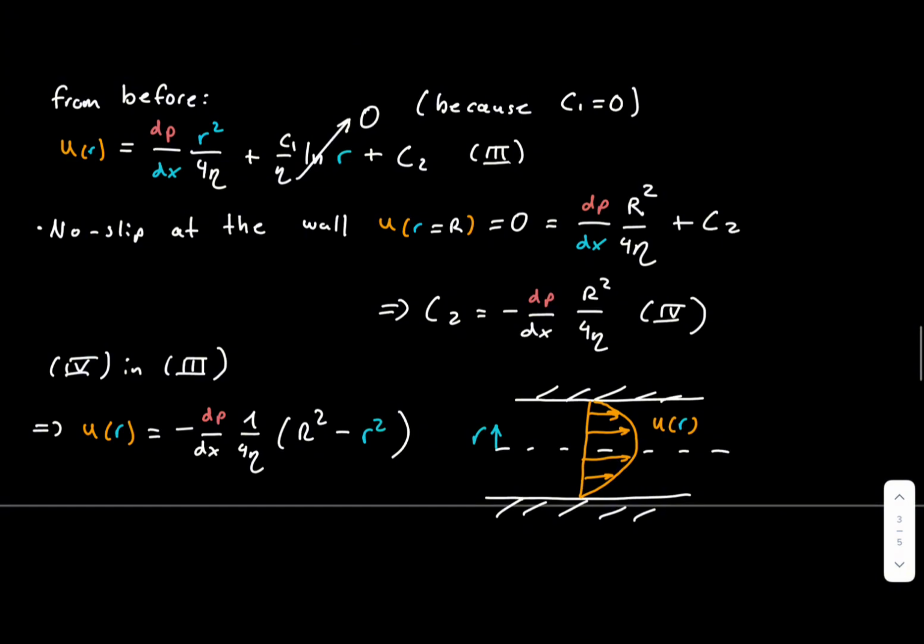And that's the full strategy. Define the geometry, choose the correct control volume, write the momentum balance before choosing a fluid model, integrate once for shear stress, choose the constitutive law, integrate again for velocity, apply symmetry and no slip boundary conditions, and finally check the signs and physical meaning. If you master this sequence, you can solve laminar flow problems in pipes, between plates, and in many other geometries, even when the fluid model changes.